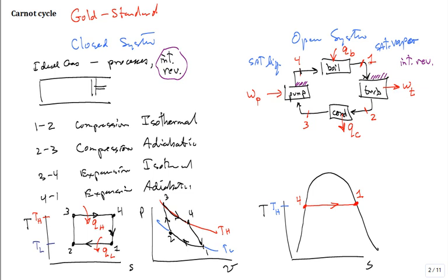That's fine, because it makes it line up with the TS diagram a little better. But that's a minor point. Now that we expand it through this turbine, what type of expansion? Completely reversible, no heat transfer, hence isentropic from the second law. It's straight down on a TS diagram.